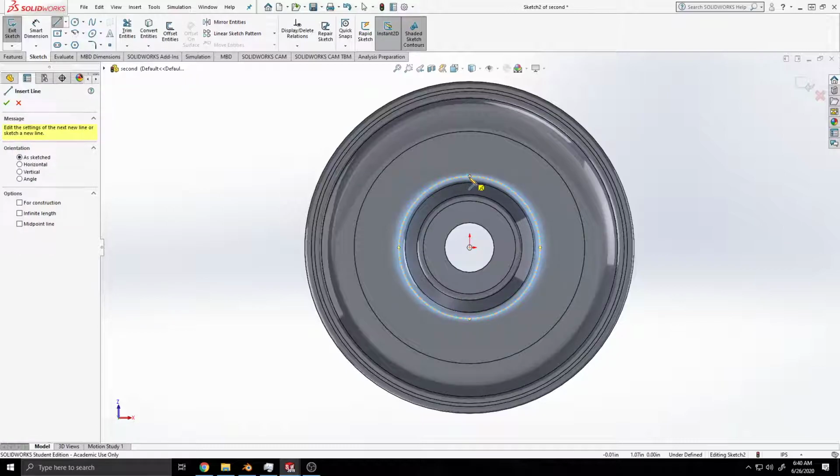When you're using the rib tool, remember, never draw the profile on the surface where the rib ends. Technically, you're starting it at the very top, and that's where Solidworks thinks of it as beginning. It could go to the side, too, like 90 degrees, but for the most part, that's where it should be. Now go to Features.